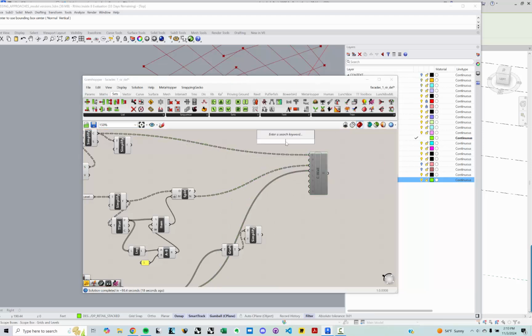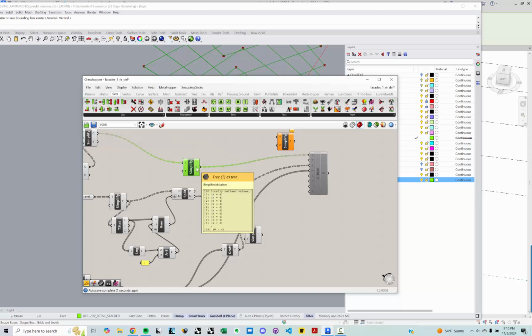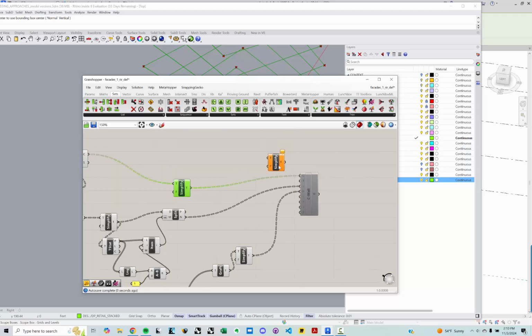It's pretty good practice to make sure your data trees match format. Sometimes it's automatic, oh, I already have a simplify on there. So that should be simplified coming in there, all just 0 to 29 in brackets. Plug my heights in there, delete this, and now if I enable this, it's going to think for a second, but all my heights will be accurate. So that's just a lesson in making sure your data trees match up when you're plugging them in.